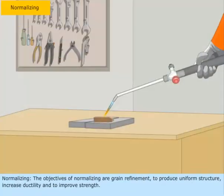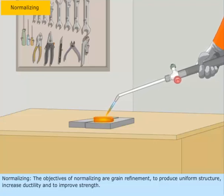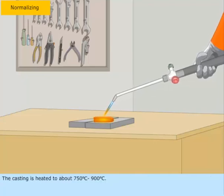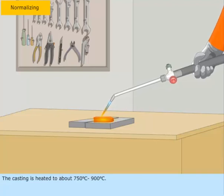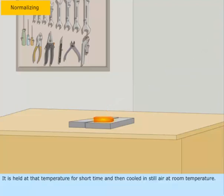Normalizing. The objectives of normalizing are grain refinement to produce a uniform structure, increase ductility, and improve strength. The casting is heated to about 750 degrees Celsius to 900 degrees Celsius. It is held at that temperature for a short time and then cooled in still air at room temperature. The more rapid cooling of the material gives a better, closer-grained surface finish.